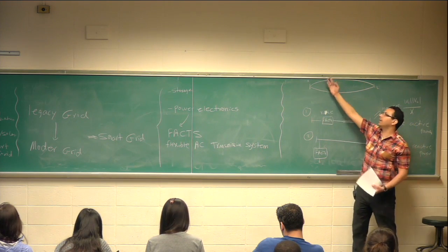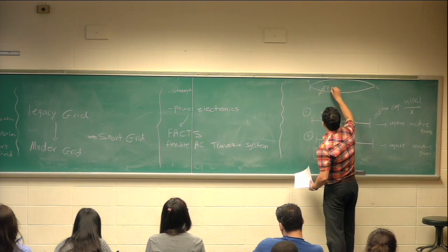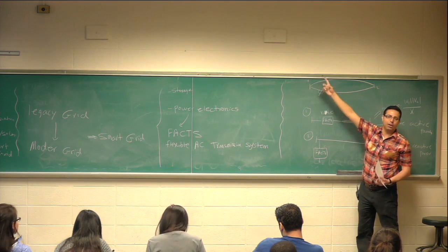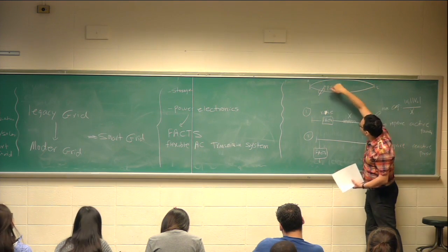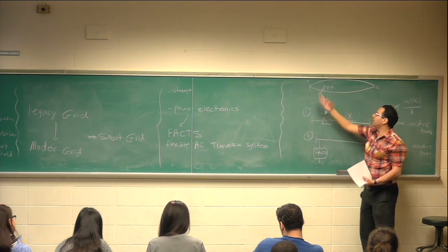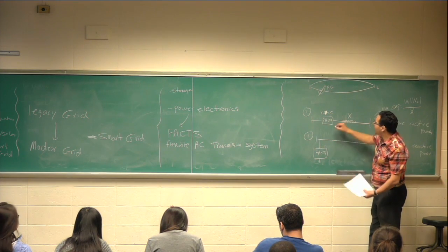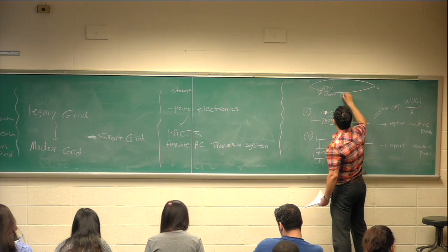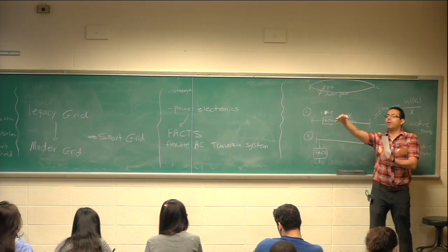How can I make it 20/80? Remember we said if I put a phase shifting transformer to change the phase, then I can control it. Because the power here depends on the difference between phases. So if I can change the phase of a device, the phase of a line, I'm good. And we talk about three-phase transformers. So another application of FACTS is change phase. If I change phase, I can route power. Instead of sending power here, I would just send power over another line.